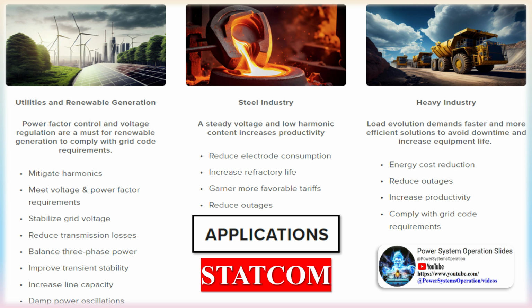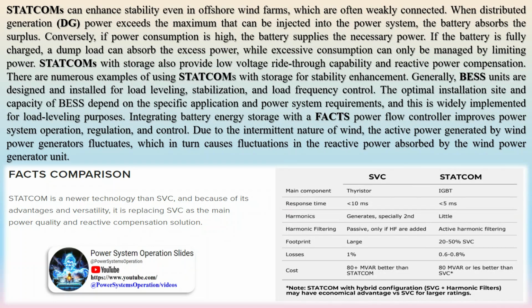The pulsating torque at blade passing frequencies causes variations in the slip of the wind power generator around its normal operating point, significantly affecting the turbine's terminal voltage. This variation is also influenced by the active power output of the wind turbine, causing changes in voltage drop across the distribution circuit. The voltage drop can be divided into horizontal and vertical components, corresponding to the in-phase and quadrature components of the grid impedance voltage, respectively.